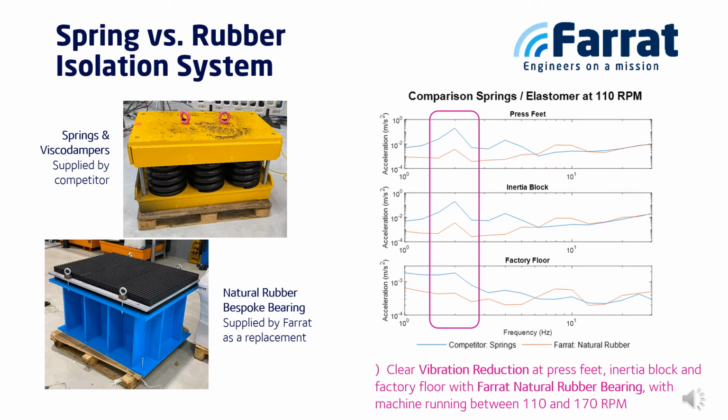A vibration reduction definitely appears on each part of the system. It is particularly clear at the operational speed of the press, slightly below 2 Hz. This is the frequency of interest since it is where the machine as a whole is likely to be moving and rocking. These are the vibrations that can be perceived and impact the process quality. It has been noted that these results were observed at all measured operational machine speeds between 110 and 170 RPM.